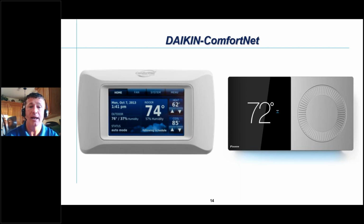Even if our outdoor unit has an inverter compressor and it is modulating, typically between 35 and 100%, or if we have a variable speed blower that's modulating the same way, or if we have a modulating gas valve, we're not using just a switch anymore. We're actually looking for different demand levels. So we use a 5-volt DC signal to do that, but we still have things like humidifiers that we need to run. We still have UV lights to turn on. We still have things that operate on switches.